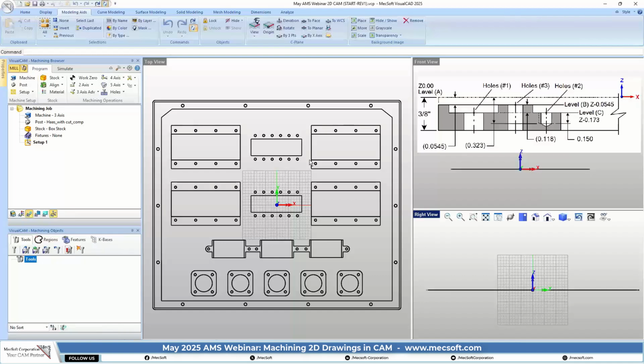So your drive regions need to be a surface to calculate the normal direction of the spindle, because the spindle is going to orient itself in an orientation that's at right angles to any point on that drive surface. So that's what's going to orient the spindle for you. You can't do that with a mesh. You've got to have a surface, preferably a NURBS surface.